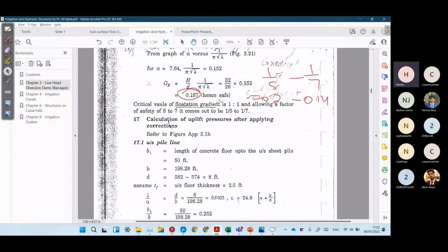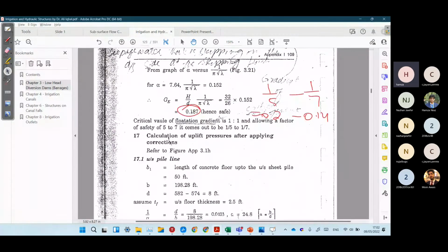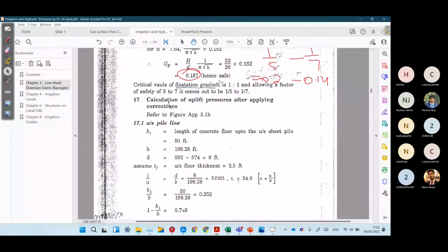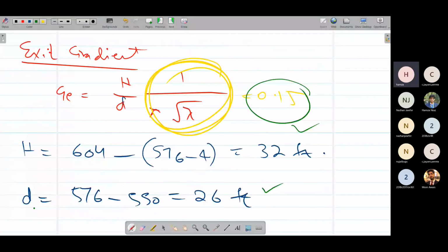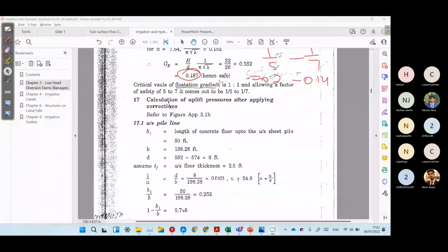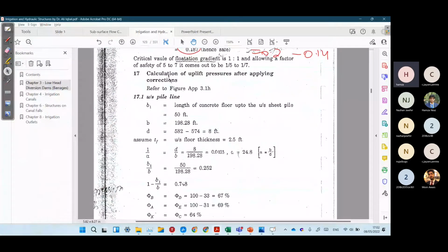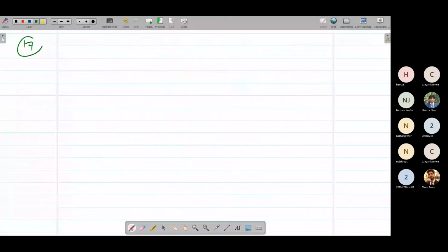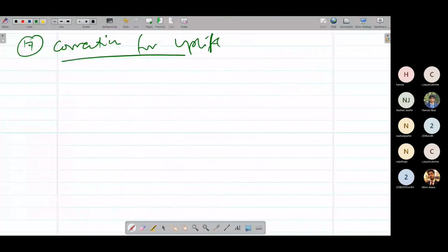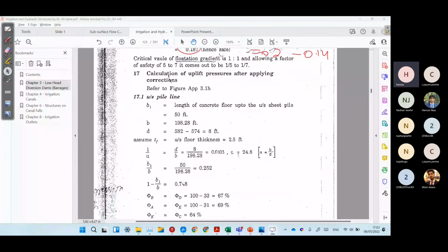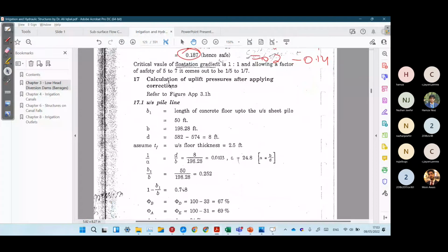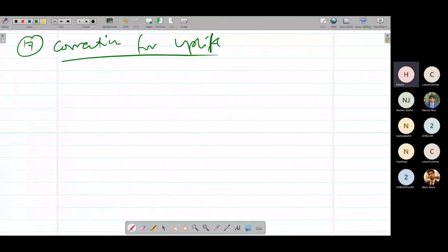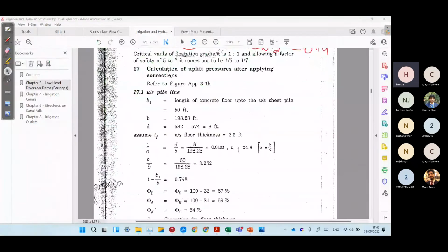This way we can calculate the sheet pile length and the sheet pile's downstream reduced levels and bottom reduced levels. Afterwards, the only different step is the correction for uplift pressures. For the correction for uplift pressures, we have three different types of piles. First of all, we use it for upstream piles. We have to do the same step for downstream and intermediate piles.